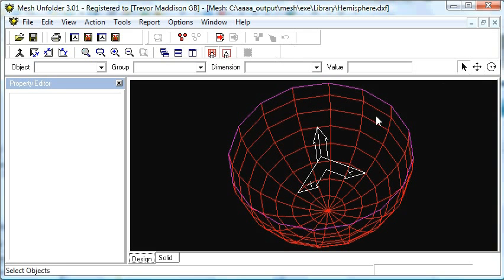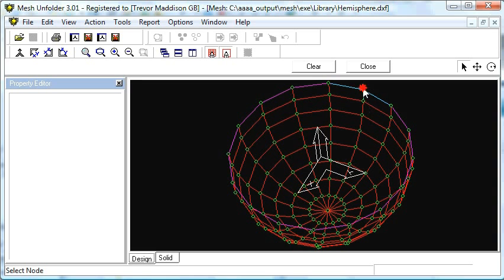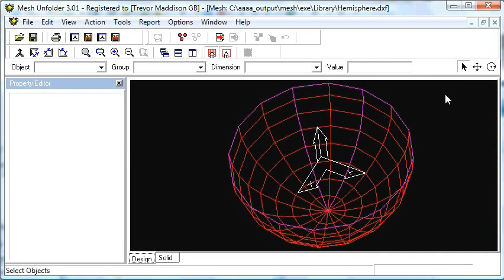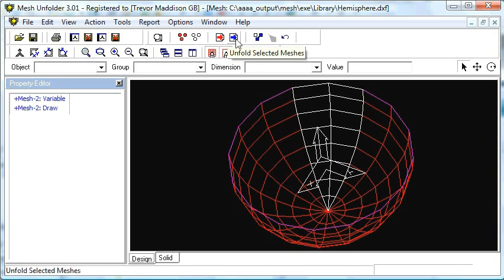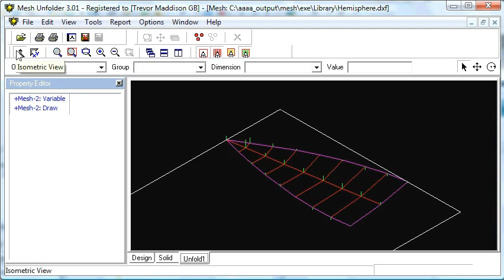Now if I want to cause a separation or take a segment of this out, I can select from there to there to there, for example, and split that, and now I've got not one part but two parts. That's one part and that's the other part. Double select again. Now if I want to unfold this as the selected part, I can just say unfold. There it is, and the stress levels in that are going to be much lower. So that's one way of creating a 3D design, from inflatables, sails, upholstery, shoes, all kinds of things like that.